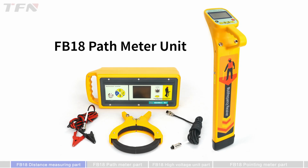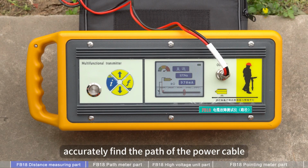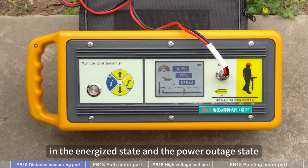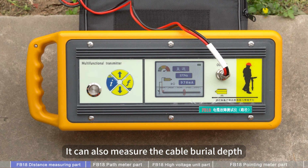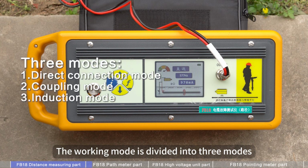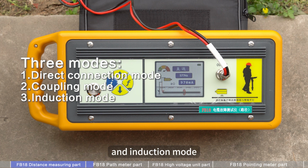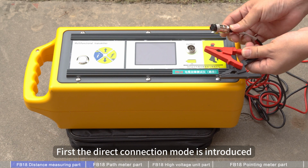FB18 path unit. The FB18 path meter with an output power of 10 watts accurately finds the path of the power cable in the energized state and the power outage state. It can also measure the cable burial depth. The working mode is divided into 3 modes: direct connection mode, coupling mode, and induction mode. First, the direct connection mode is introduced.